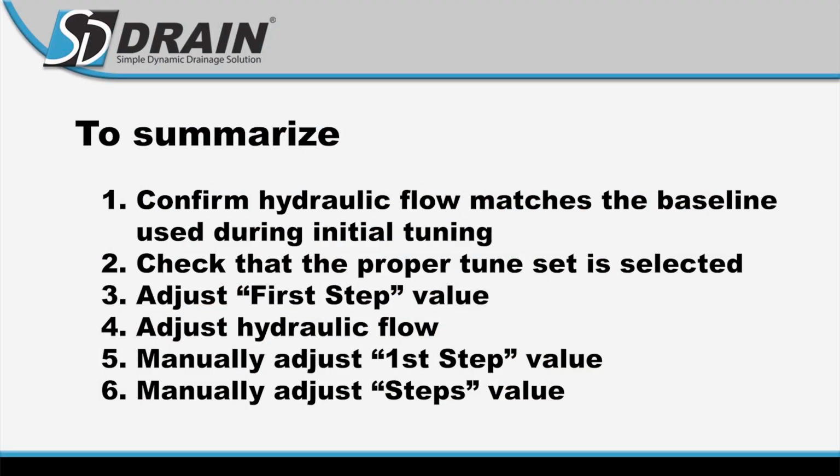To summarize, confirm hydraulic flow matches the baseline used during initial tuning. Check that the proper tune set is selected. Adjust first step value. Adjust hydraulic flow. Manually adjust first step value. Manually adjust steps value.